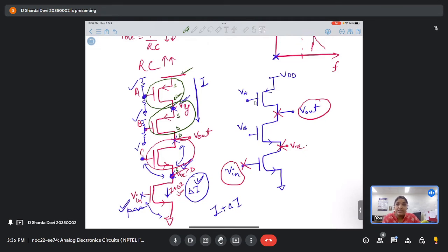DC never changes, DC will remain constant. What you can change is basically the floating nodes which don't have any fixed values. If I connect, let's say, Vy to VDD, no matter what you do, you can never change this VDD. Is this clear?